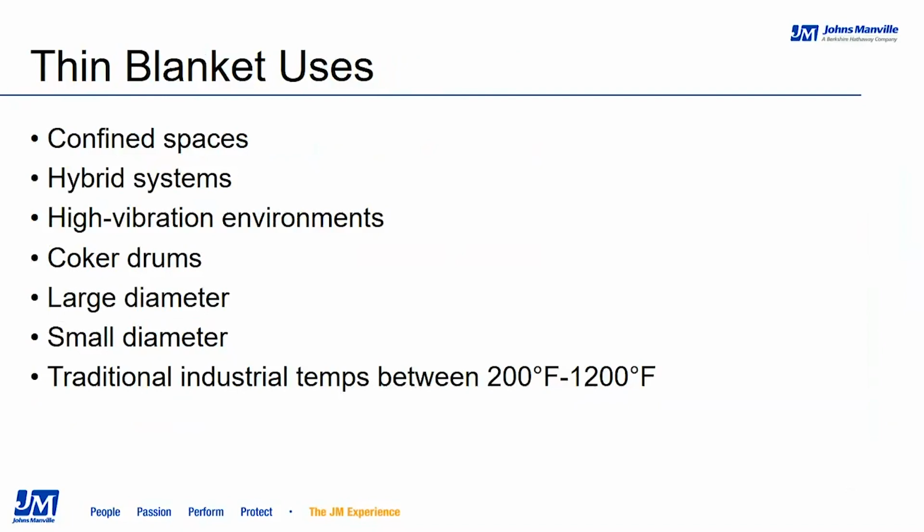Another prominent application is high vibration environments. Again, with mineral wool binder burnout in a high vibration environment, the structural integrity of the material, especially in piping applications, can be compromised, causing material sagging on the pipe, which can dramatically affect the thermal efficiencies of the system and can allow voids in the jacketing, which could allow moisture in, which may cause corrosion. Thin blankets, when properly installed, significantly mitigate the risk of structural degradation in material due to vibration. Kim will expand on this greatly and show you some compelling test data detailing our superior performance of thin blankets versus traditional insulations in high vibration environments.